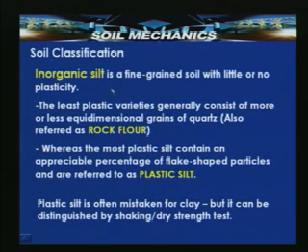The least plastic varieties generally consist of more or less equidimensional grains of quartz, also referred to as rock flour, whereas the most plastic silt contains an appreciable percentage of flake shaped particles and is referred to as plastic silt.